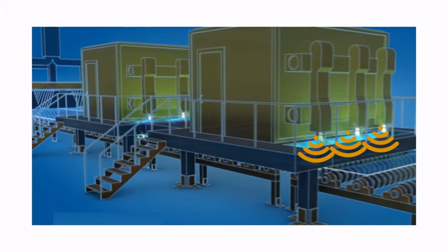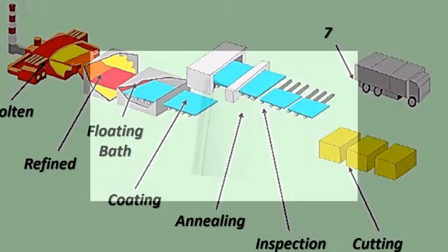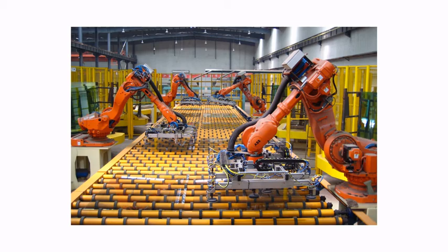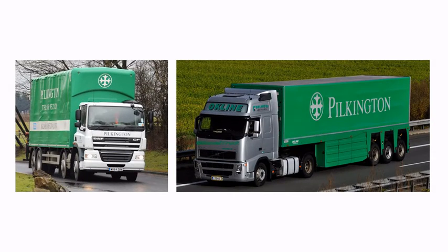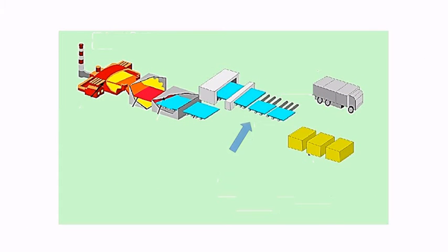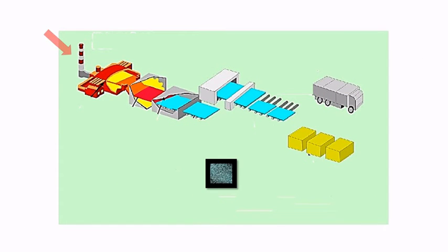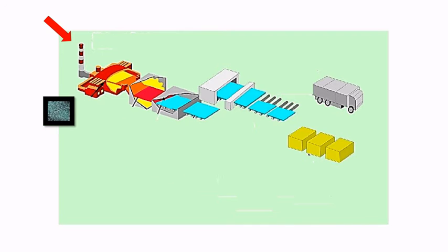The sixth is the cutting. In order to obtain the most usable parts possible, diamond wheels are used by Pilkington to trim the selvage, following the measurements indicated by the computer according to the client's order. The excess glass in this operation is reused in the mixing process, so none of the material is wasted.